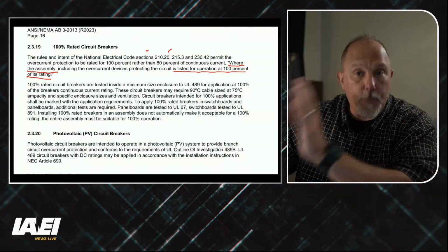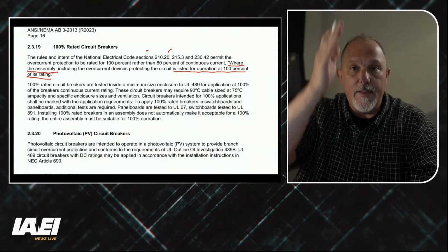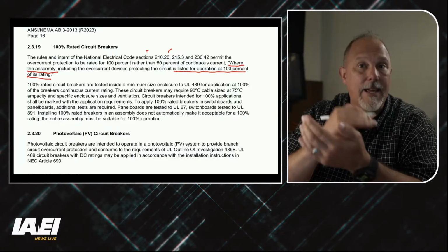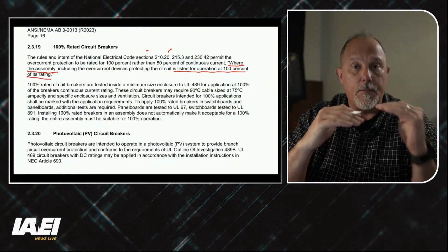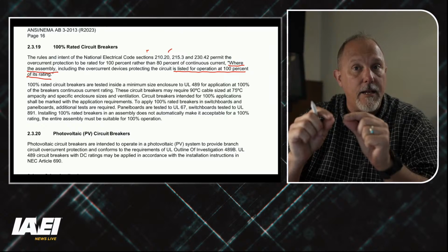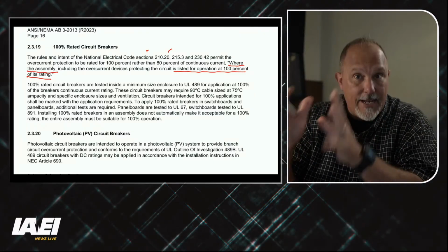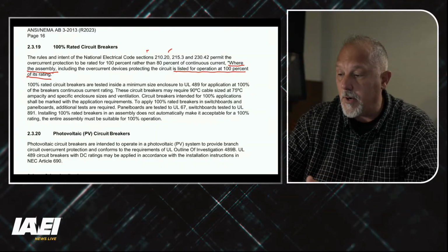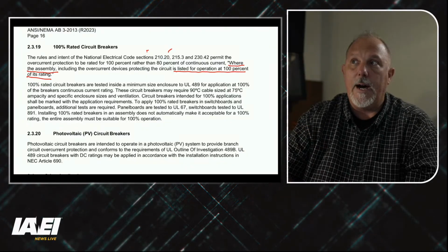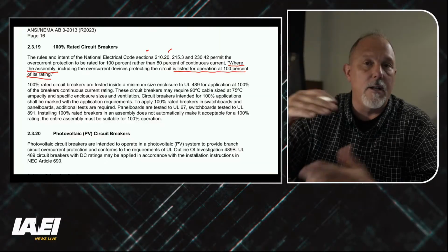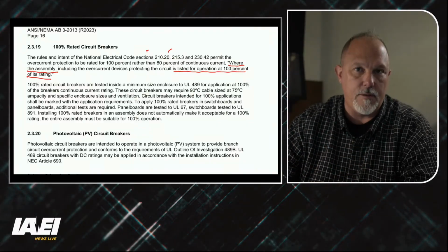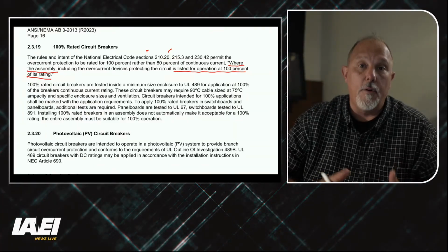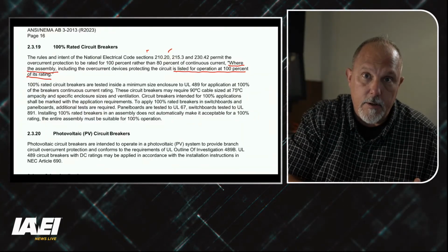We go to Table 310.16, and whatever that value is for the size of a conductor that you're going to place on it, you can't go any higher in the overcurrent protection than that rating to provide the protection of the equipment. If I have a circuit breaker and the 75 degree C column says 200 amps, I can't exceed 200 amps for that circuit breaker.